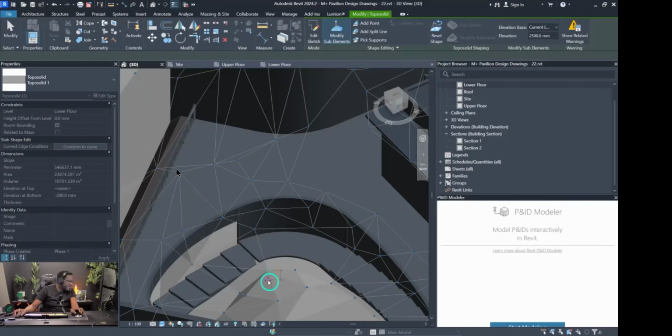Right, guys, so this is how you modify the terrain to match anything that you put in the terrain, right? So if you're working on a site that has any kind of stairs or roadway or ramp, and the ramp needs to follow the terrain, right? You build your terrain first, you build your ramp, and then you go back into your terrain and add some new points on the edges of that ramp. And then you just move each one of those points up and down in 3D view. And that's how you can get your terrain to neatly follow something that you place in it.